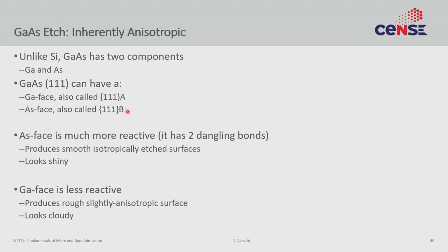To cut a long story short, it becomes increasingly harder for these complex materials to find etches that are truly isotropic, that actually etch in all directions equally. That is because there is no isotropic property that you can actually use to design an etch that is isotropic. So the canonical gallium arsenide etch is also an anisotropic etch. There is really no isotropic gallium arsenide etch per se. Okay, so that's point number 1 to remember.